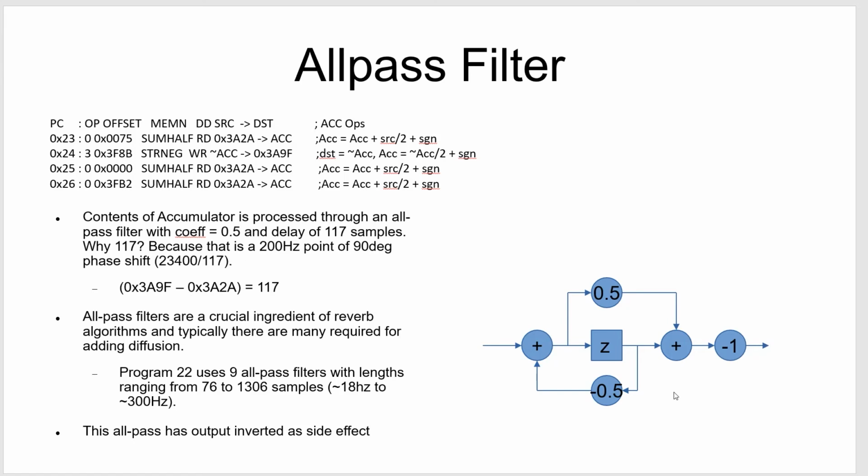Every DSP system, based on the sample rate, will have a different coefficient to set these frequencies. And in our Midiverb, the magic frequency is 23,400. So if you want a 100 hertz or a 50 hertz or a 10 kilohertz filter, that's what you do, you put that in. Notice that the higher in frequency you want to go, the more granular it is. And most of the filters used in the Midiverb are all less than 1 kilohertz.